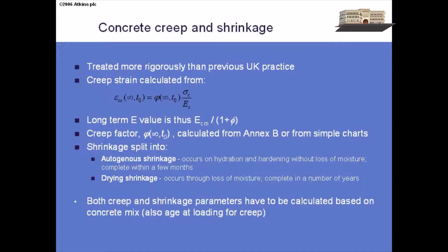There's a drying shrinkage, which is probably what we mostly think of as shrinkage. That is, as it sounds, water moving out of the concrete with time and drying. But there's also an autogenous shrinkage term, which occurs generally very quickly over the first few days, and that's basically water being absorbed in the chemical setting reaction. So the water doesn't actually migrate out of the section, it's being consumed internally, but both of those lead to shrinkage, but with different durations of time.